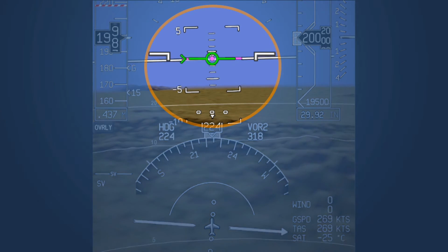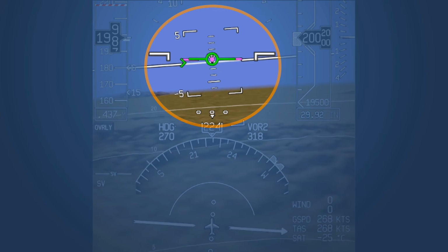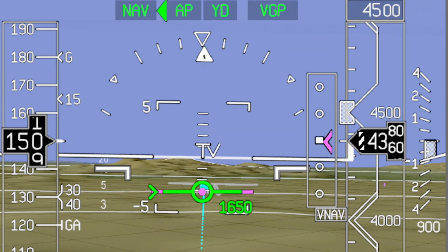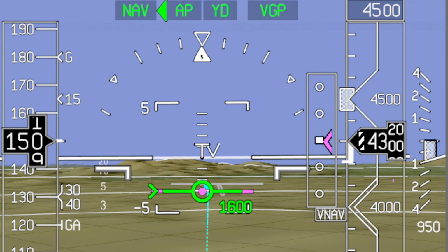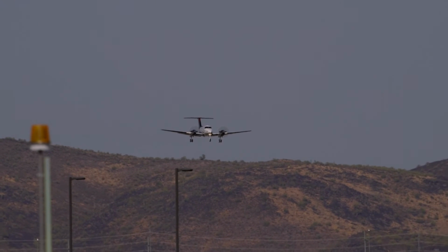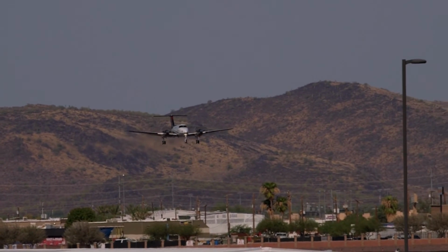The pitch ladder, in combination with the flight path symbol, represents the flight path angle of the aircraft. The 3-degree reference line is larger than the 1, 2, and 4-degree lines. The flight path symbol represents the aircraft's current flight path angle and ground track, but does not predict the future flight path. It is affected by changes in aircraft attitude, power settings, and ground speed.